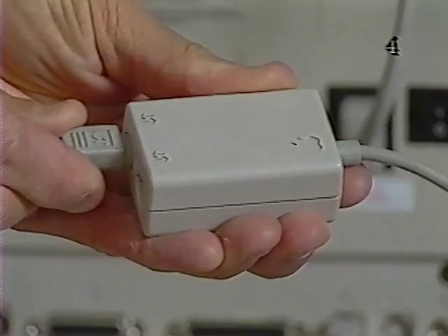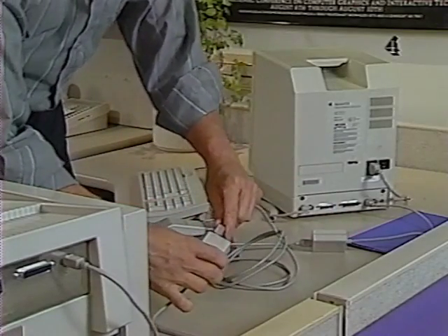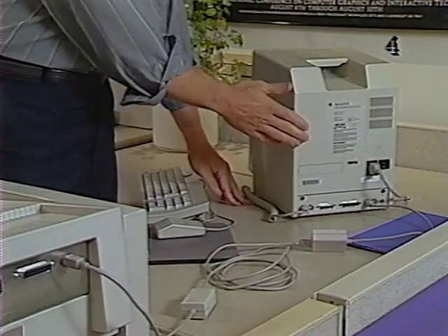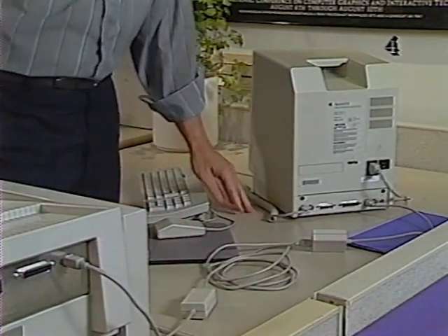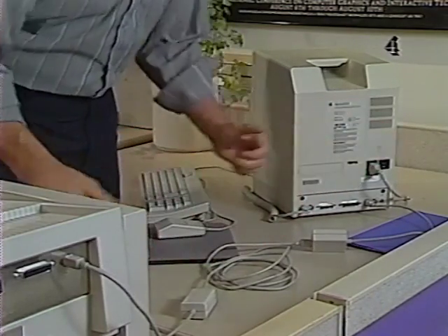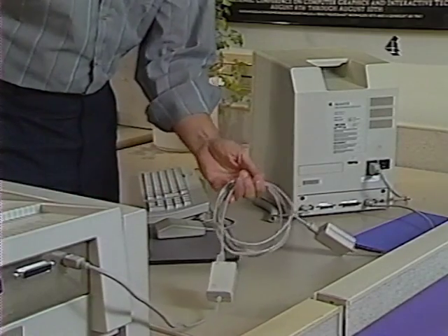Now, connect the 2-meter cable between the connector boxes. Either connector on the connector box can be used. Repeat these procedures for each additional computer which is to be connected to this Personal LaserWriter. Now, if the printer and a computer are more than 2 meters apart, connect 2 2-meter cables using a cable extender.